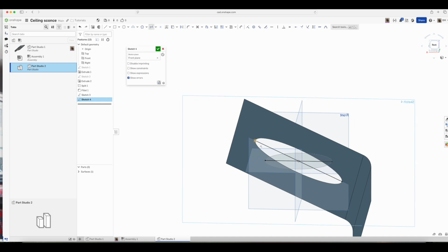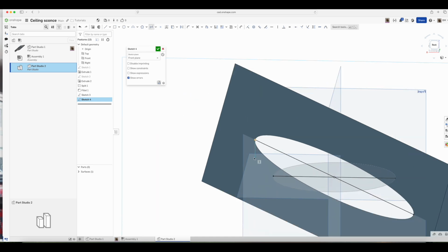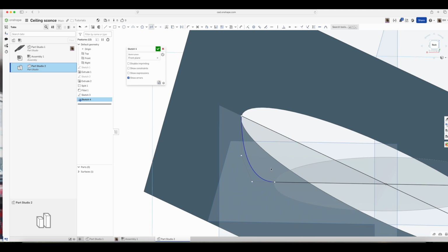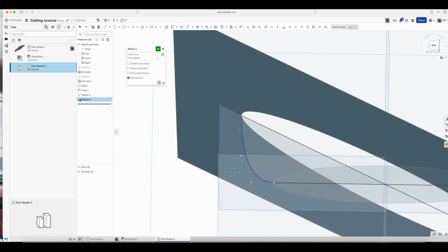And we're going to select that point. We'll select a point somewhere in the middle. We'll select a point horizontal to this point, and then we'll select that as our final point and hit escape. And so now we have this curve, and the end point here is constrained to be vertical. You can see that by hovering over top of it. You see the vertical constraint. And this is constrained to be horizontal. So you can see that there. If we hover over it, you see the horizontal constraint.